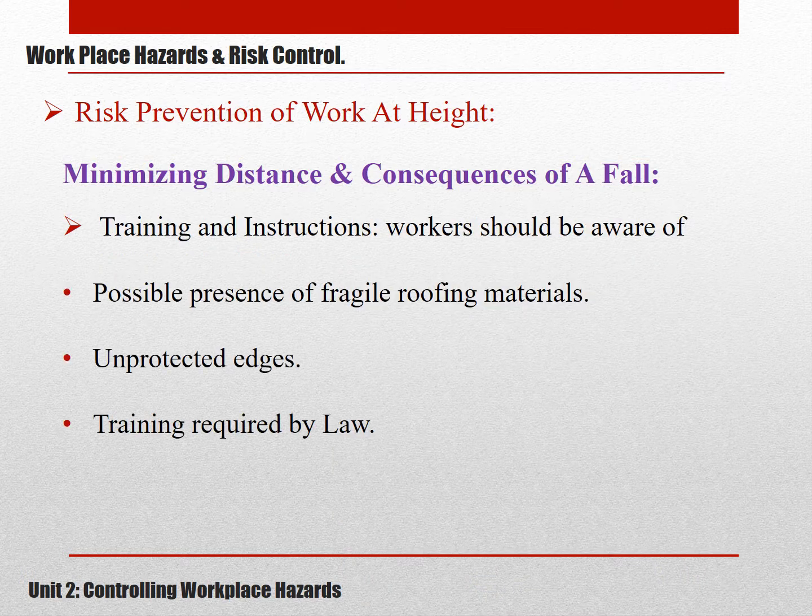The next point in this step is training and instructions. All workers should be trained in order to work at height safely, and as a minimum, workers should be aware of hazards posed, such as the possible presence of fragile roofing materials or unprotected edges. Also, some training may be required by law for the use of some equipment. For example, workers who are erecting or modifying scaffolds should all be competent, and those who are driving or using a mobile elevating work platform should have attended a recognized operator training course.